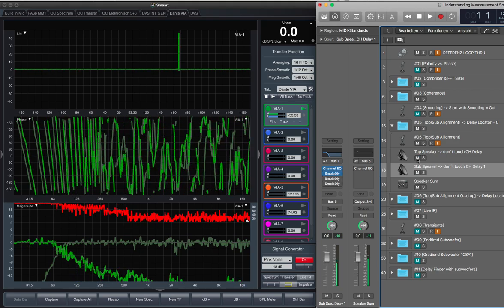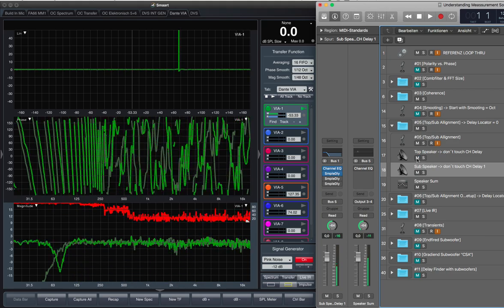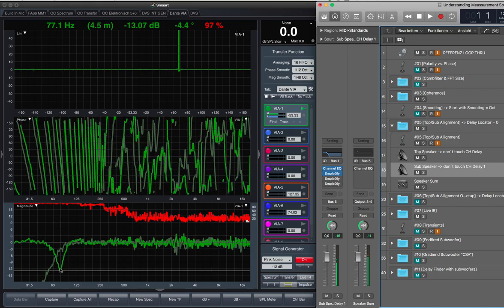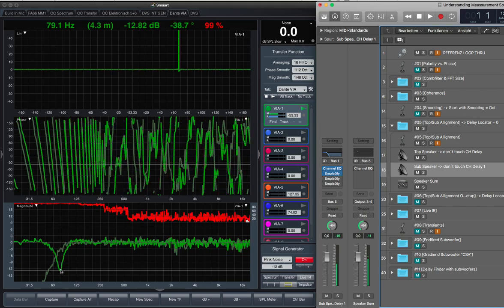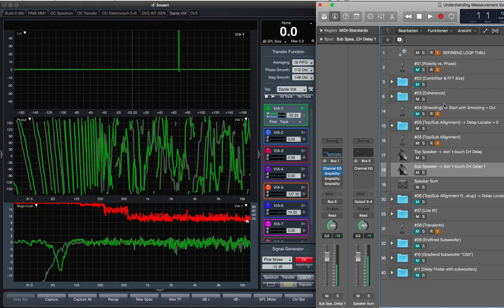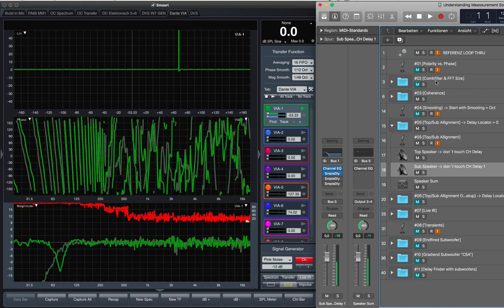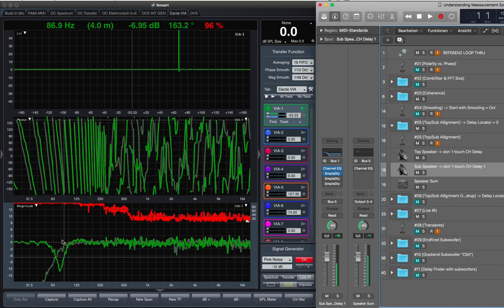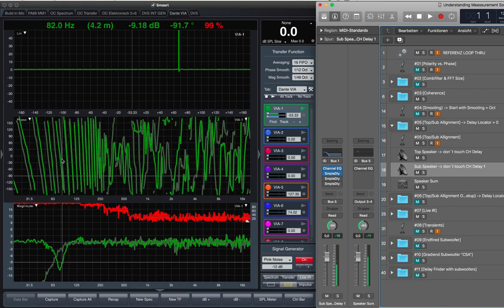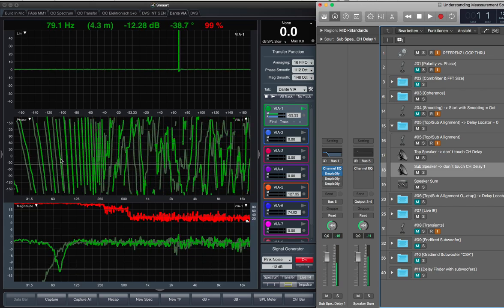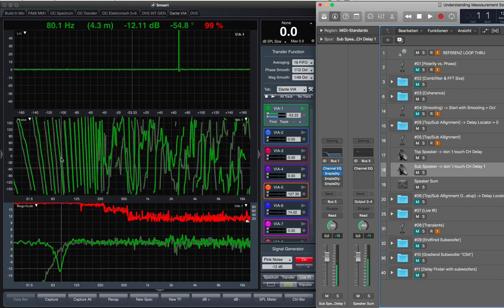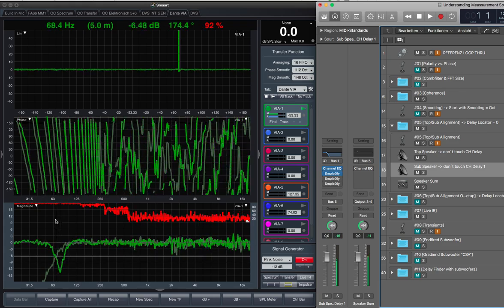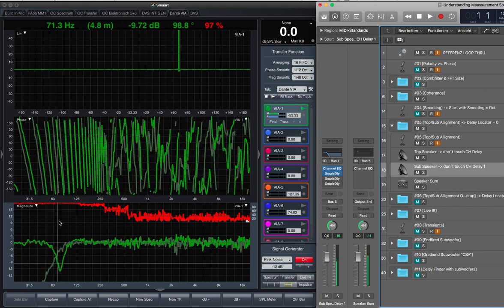And if we switch on both systems, subwoofer and top, and they are not corrected, then you can see here this dip. And what is the cause for this dip? Correct. This is the comb filtering that we have in exercise 2 here, and it's the same thing: two signals not at the same time, so they cancel out, where the frequency has a 180 degrees shift. In the last third of the phase wheel, we have destructive interference and cancellation.